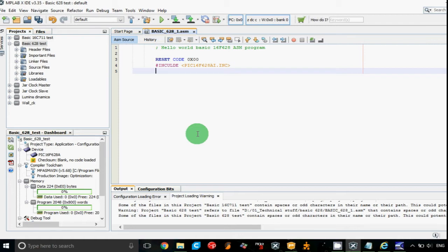We're just gonna write some configuration pins for this microcontroller. Probably there are some fuses that they need to be set in order to have them set when you program the microcontroller. One of the fuses would be, for instance, the type of external or internal oscillator you want to use for this microcontroller. And by declaring these fuses here, you don't have to set them again in the programming environment for the microcontroller.